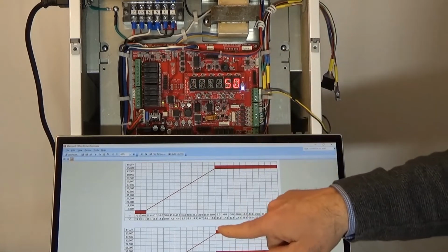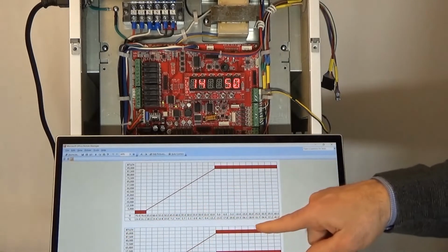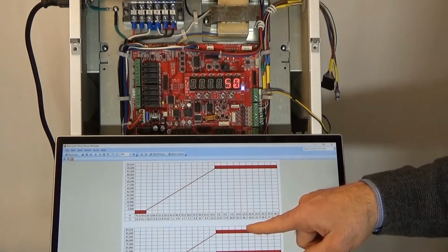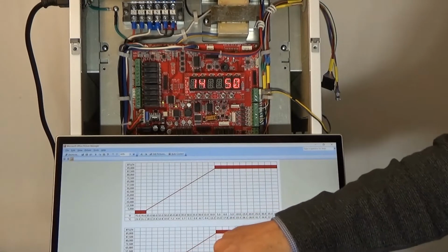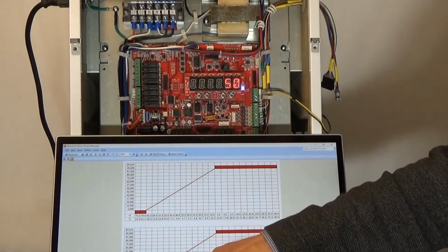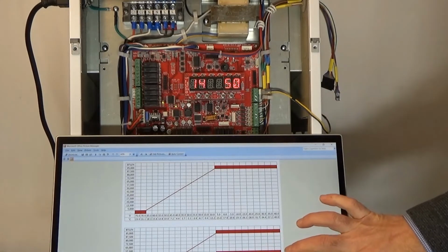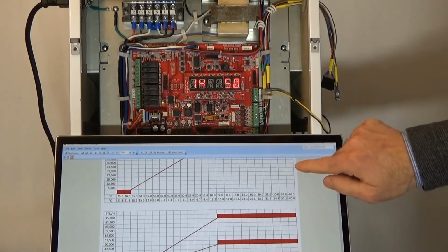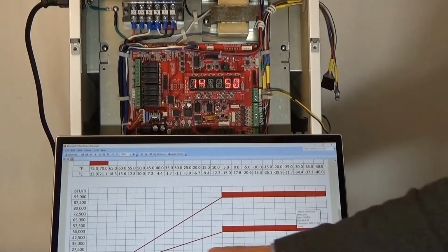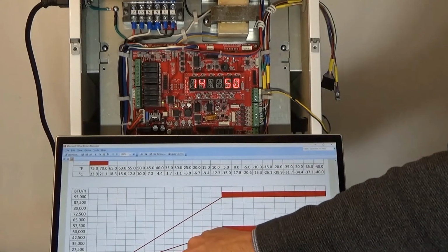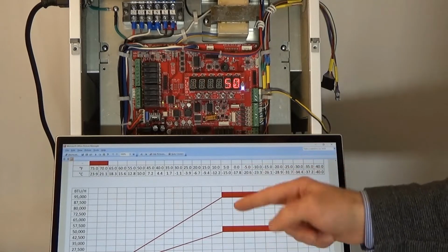And what that does is, even though I might have the 18,000 series that does 95, I've told the unit I don't need 95, I only need 50. So it actually drops the curve, and what that does is at any point in the curve, now you'll see that, let me just expand this up for you a little. We can look at it. So that at any point on the curve, now I'm going to be delivering lower BTUs because my total maximum load is now set lower.